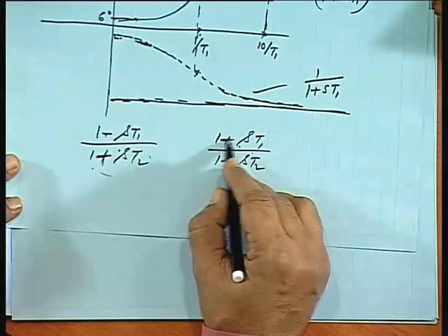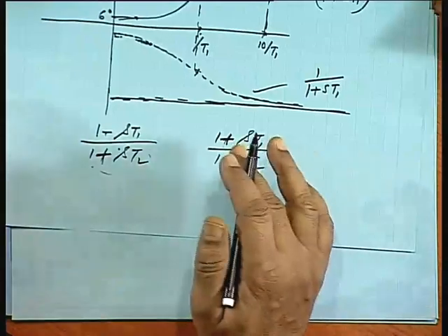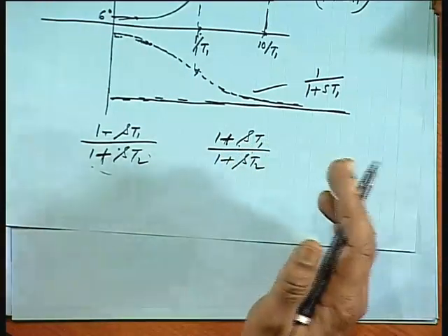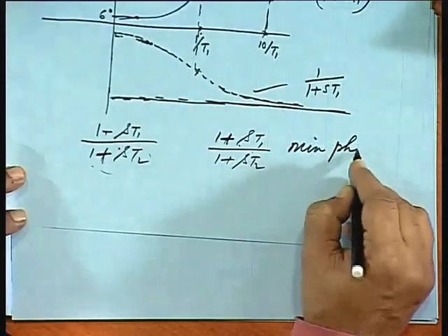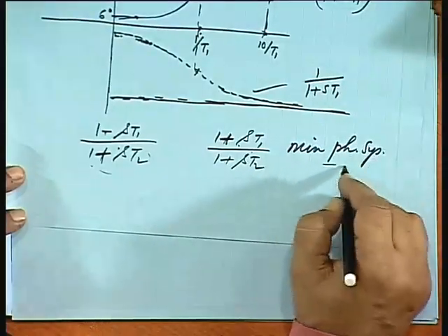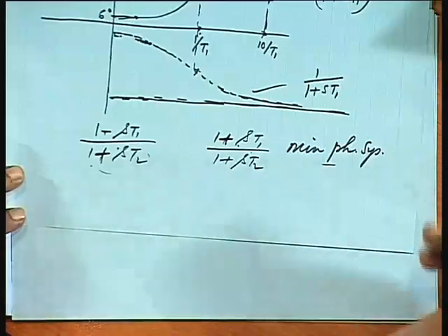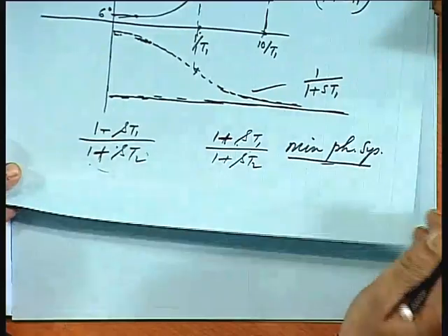So, when all roots are in the left half plane, that is both poles and zeros are in the left half plane, we call it a minimum phase system. So, we can realize only minimum phase system like minimum resistance, minimum reactance functions we were discussing earlier for network functions. Similarly, for a transfer function from Bode plot we can realize only minimum phase system.